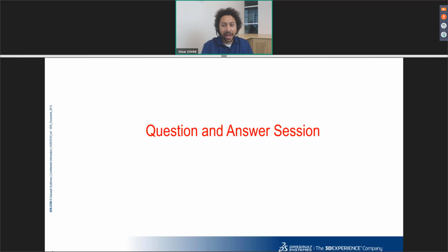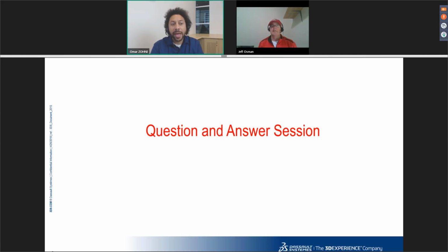The third question, and Jeff Osmond is going to answer this one. So Jeff, if you want to pull up your webcam, what is the benefit of using the runner wizard? Is it more accurate than modeling it in 3D? Great question. It's not so much accurate. I believe it was brought up once before that you don't have to start with sketch lines. You can basically real quickly put down some runners, even the sprue and gates, fairly quickly.